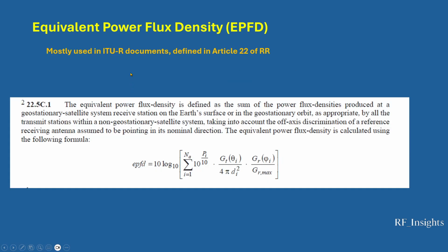There's another concept that is closely related to PFD. It's called equivalent power flux density, or EPFD, which is very common in the ITU documents. If you're familiar with the ITU radio regulations, the Article 22, for example, which defines the formula for the EPFD, deals only with the EPFD values to protect the geostationary satellite systems. So this snapshot here on this page is from the Article 22. It defines the EPFD with this formula.